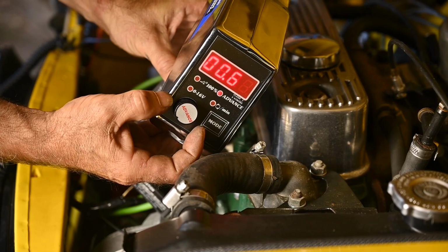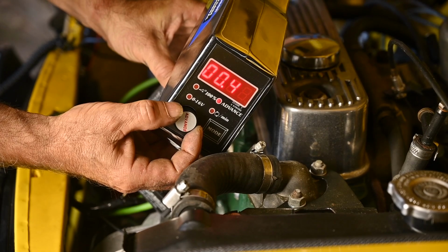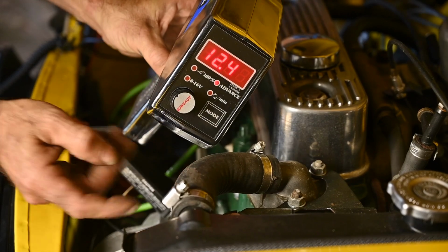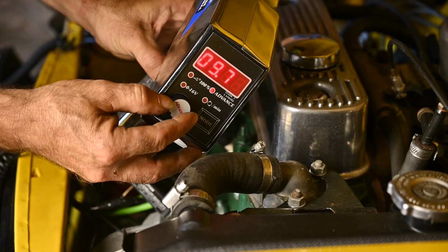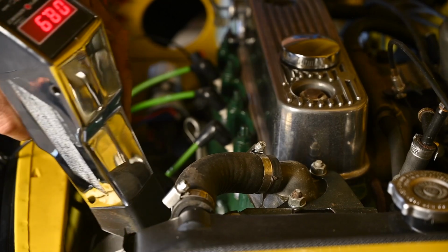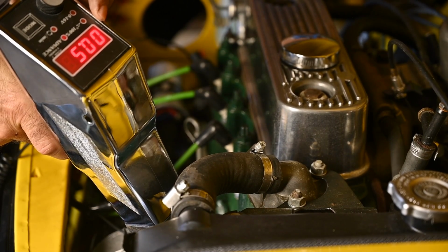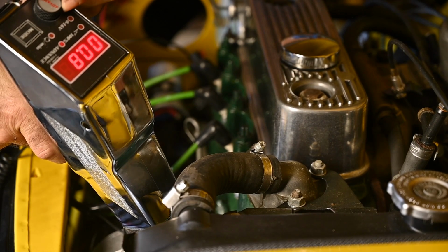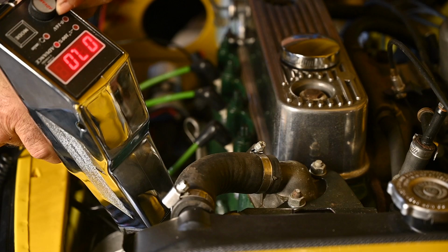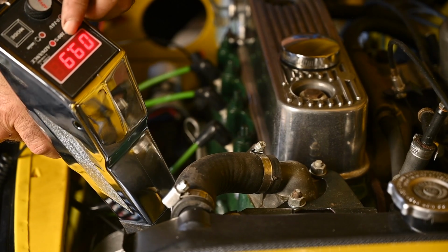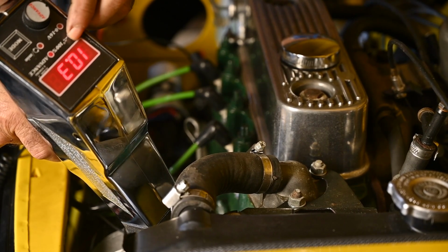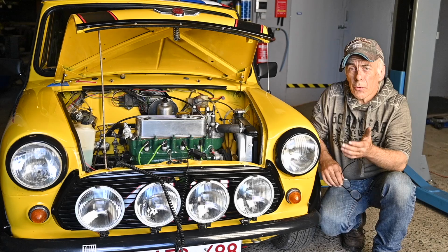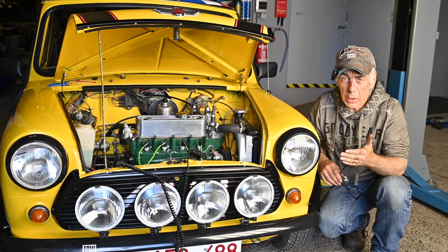With this strobe light I can actually set the advance in degrees. So I can set it to, like, 8 degrees, and I should see the point moving on the pulley then. But right now I'm going to set it to 0. I'm going to flash one more time inside, increase the degrees on my strobe here, and I should see the mark on my pulley moving forward and lining up actually with 0 or top dead center. And what I see here is I have about 10 degrees advance, as you can see, and that's the advance I wanted to get.